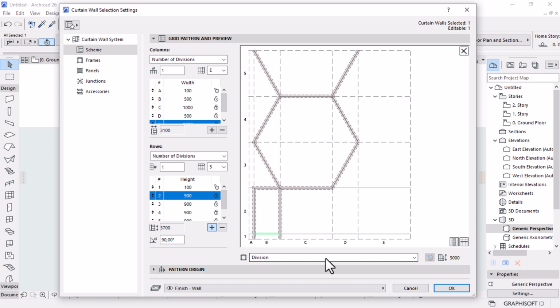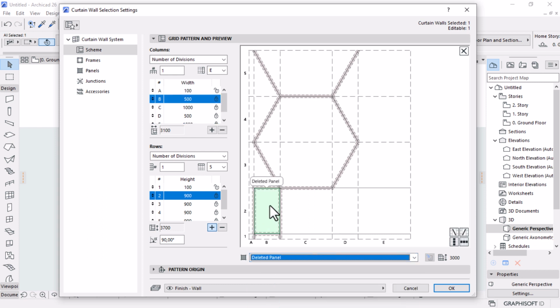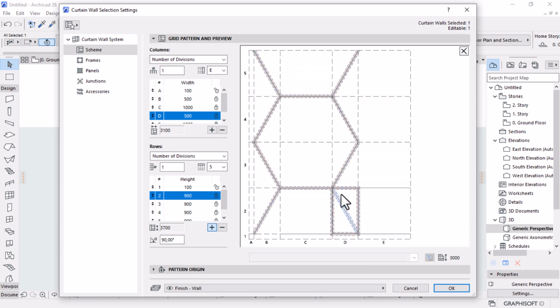Okay, so that we can select this line, make it transom in order for us to select the panel, and the panel is going to be this direction, right? We can get rid of our frames. We no longer need them because they've served their purpose. Unfortunately, you cannot mirror this to the other side. You have to go through this process. Okay, select this grid for the panel, change the frames to transom, and then select the panel alone. Make sure it's diagonal. Okay, so let's get rid of these lines like that.